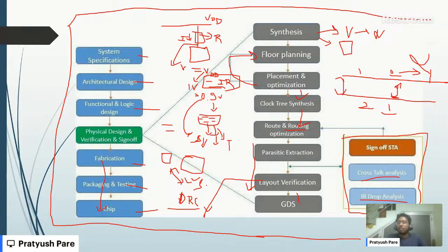Yeah, Mahek Kumar, the synthesis tool used for FPGA and ASIC are not the same. Because in FPGA we aim for very optimized synthesis. We have lots of logic elements, and synthesis is dependent on the tech node we are using. So for every FPGA board there will be a different tech. Yeah, so it is independent, I would say. For ASIC design, we use a very advanced level of synthesis tool, which is not required at FPGA level.